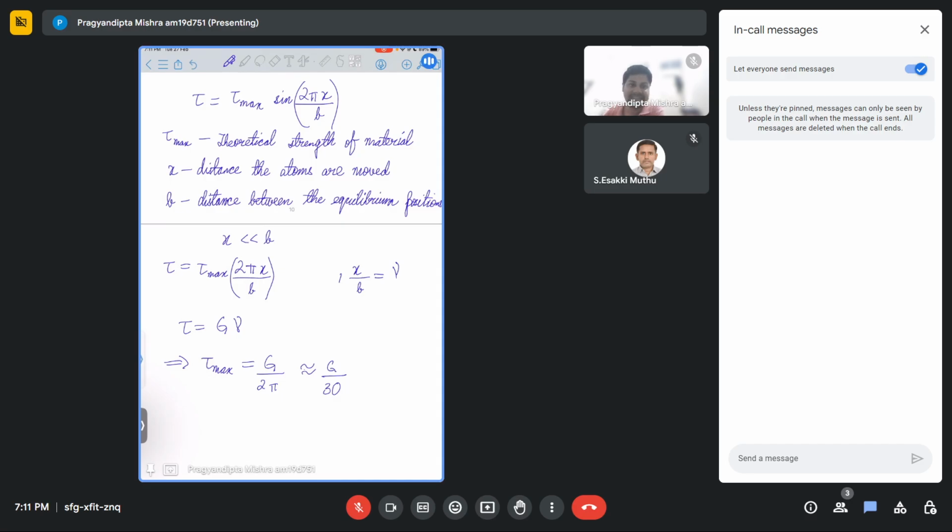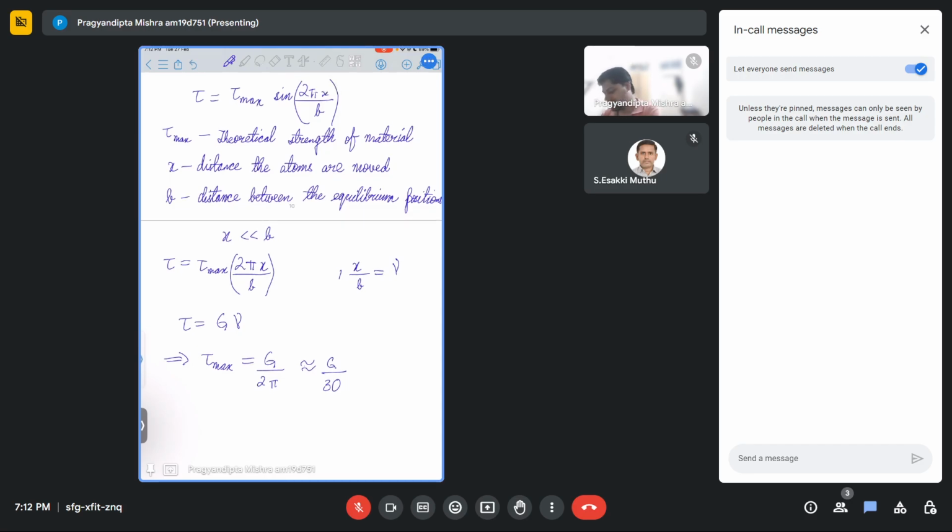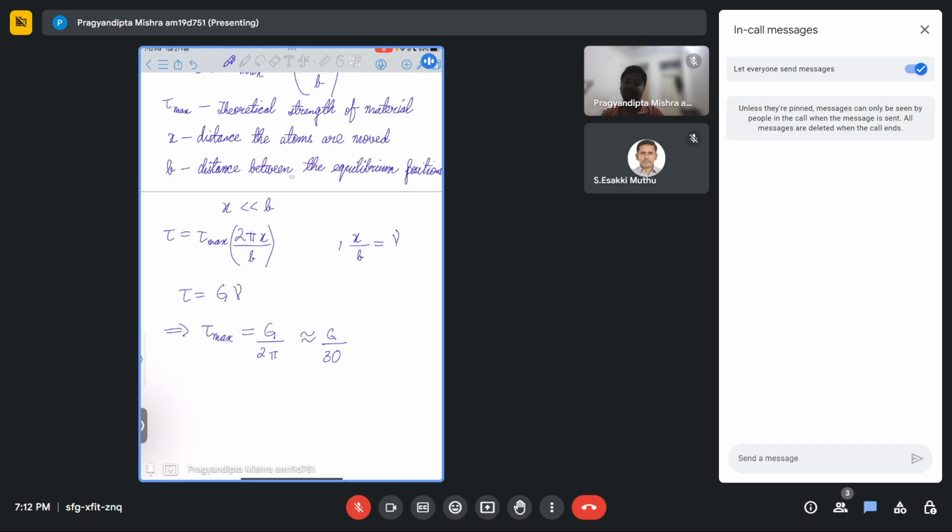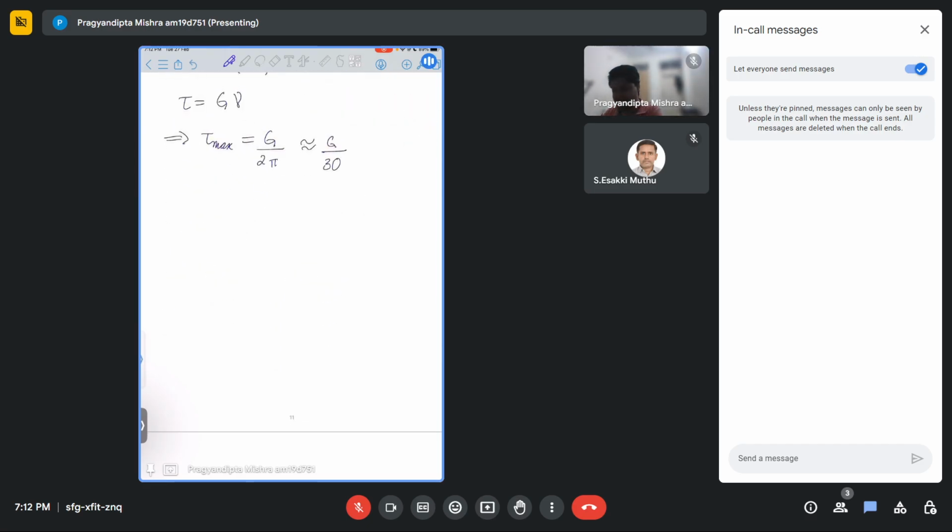So dislocation essentially makes it easier for us to deform the material. Otherwise, it will become very difficult for us to deform the material. We will have to keep applying load till we reach some very high value, after which the failure would be very sudden. So dislocation essentially helps in ensuring that plastic flow and ductility happen, and the material starts deforming before it fails. Okay. So this is how people discovered that dislocations were actually present in the material system, and they were able to convincingly prove that dislocations are present in any system.